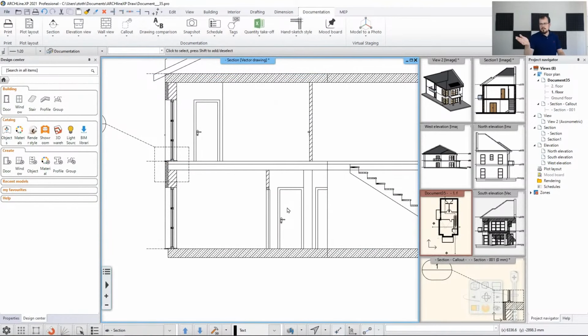Now, what is happening on the section? I don't see any hatches. This is because in certain cases, updating the 3D and the sections is transactional, so you have to manually click on the 3D hammer in order to update these changes. Why is that so? Because sometimes you don't want all changes to be reflected. If it were automatically refreshed all the time, that might be a bit time consuming on your processor, so in these cases you have to do this manually, but that's okay.